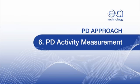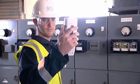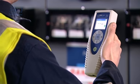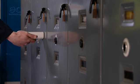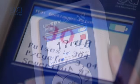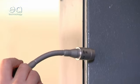PD activity measurement. Want more information about PD activity? Choose the Ultra-TEV Plus. It uses the same dual sensor technology as the Ultra-TEV detector, and it works just as well as a first-pass fault detector, but with a lot more features, including a color screen showing details of PD activity as numerical and graphical values, plus a set of headphones and a microphone so you can listen to PD activity as audible signals.